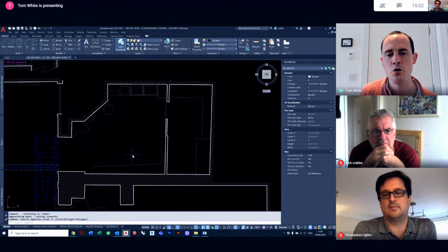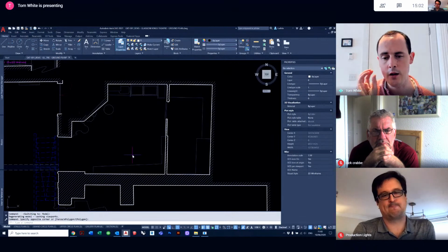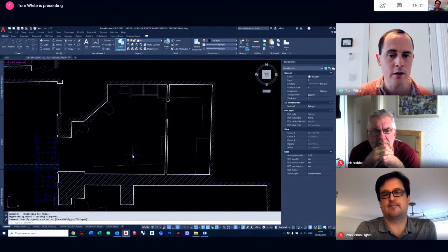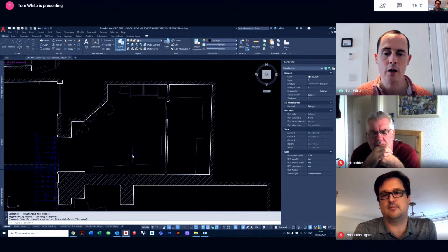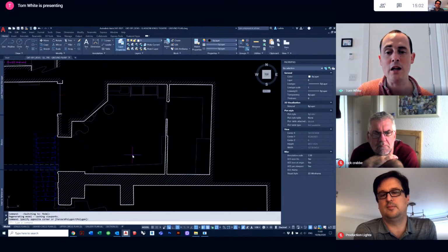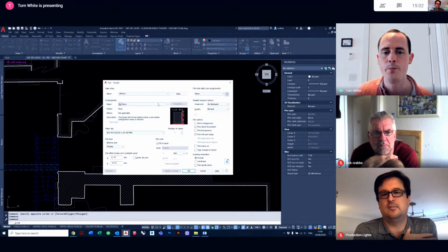The reason why you might choose not to print in this location is this: I'm going to print this drawing and send it to Dick to comment on, and Dick's going to comment on a few things. I would like to have a follow-up conversation with him to send his comments back. But what if I print it in model space? I can't necessarily do an exact replication of what I've sent him in the first place, and therefore, to make it presentable to him, ideally I'll do a layout in paper space. But nonetheless, like in any program, Control P to print or plot.